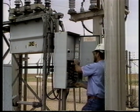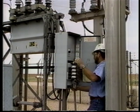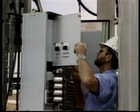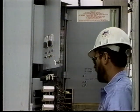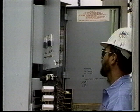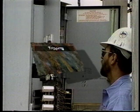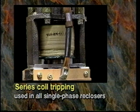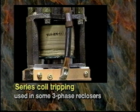The electronic control conveniently permits changing timing, trip current levels, and sequences of recloser operations without de-energizing or untanking the recloser. Tripping. Series coil and non-series coil tripping are characteristics of individual classifications of reclosers. Series coil tripping is used on all single-phase reclosers and some three-phase reclosers.